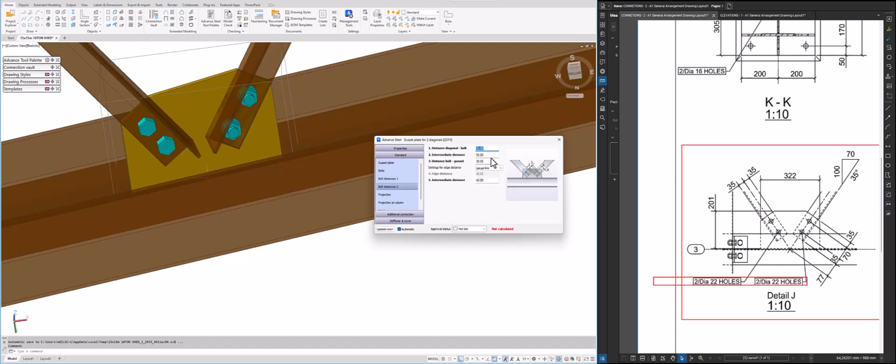That's all right. Let's do the same for the other one. And then from there, we go to center line. All right, that is done. Projections, if you want to add projections, you can add them there. But according to our design, we do not have any projections. Projection at column as well, we don't have those. Any welding set to 6 millimeter continuous fillet weld.